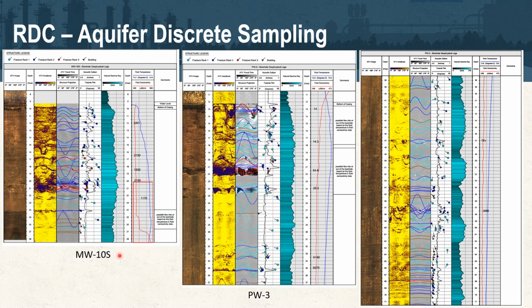If we look at the fluid temperature column on each of these 3 plots, what we can see is, at that middle graph that Derek's pointing at, if we're looking at that specific interval, the potassium permanganate did a pretty good job of remediating TCE and getting it down to low-level ppb concentration at that high K zone. But if we move further down the borehole, we can see that some of the other producing intervals present within that borehole are actually generating significantly higher concentrations of mass.